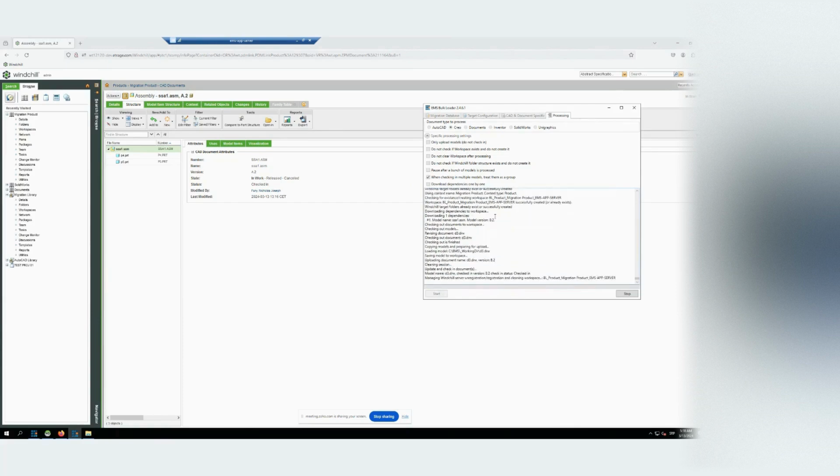Each particular assembly will be migrated as a single model. All dependencies are already migrated into Windchill, and migration of that assembly works in such a way that all dependencies are first downloaded to the workspace, and then only that assembly is migrated. Also, we can handle harness parts and migrate the harness parts along with the related assemblies in one process.